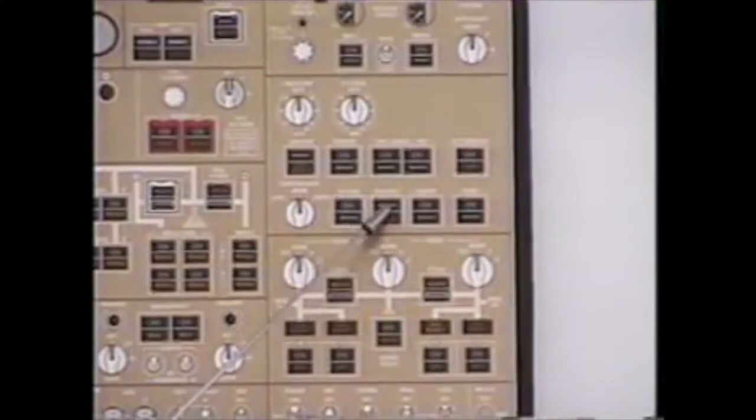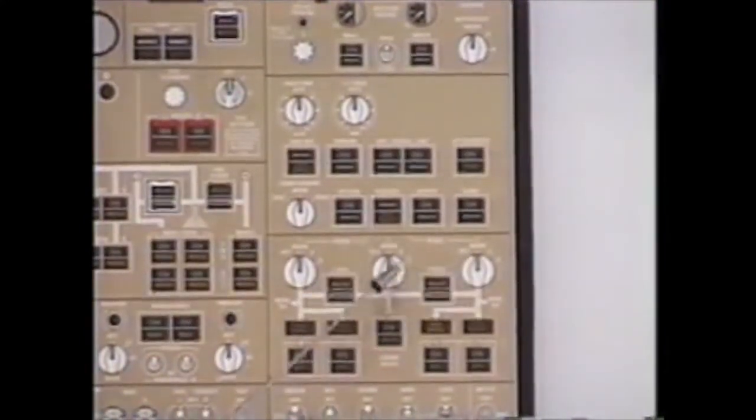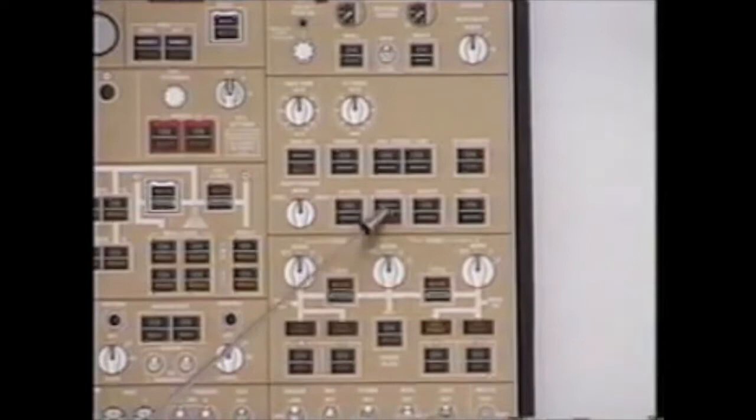Note, in the pack reset switch, we have a sys fault light which will illuminate if an air conditioning pack trips off due to a pack fault. Each pack has the ability to trip due to a pack fault individual of each other. In addition to a pack fault, pressing a cargo fire arming button for the lower compartments forward or aft will shut down pack 3. In addition to a pack fault, overpressurization on your airplane will trip pack 2.